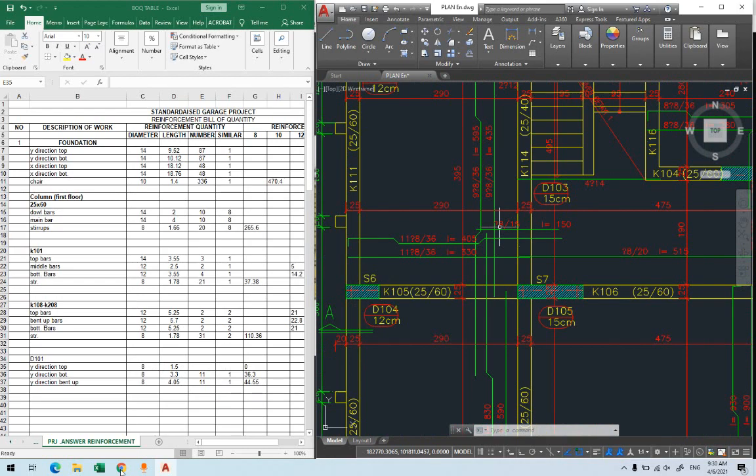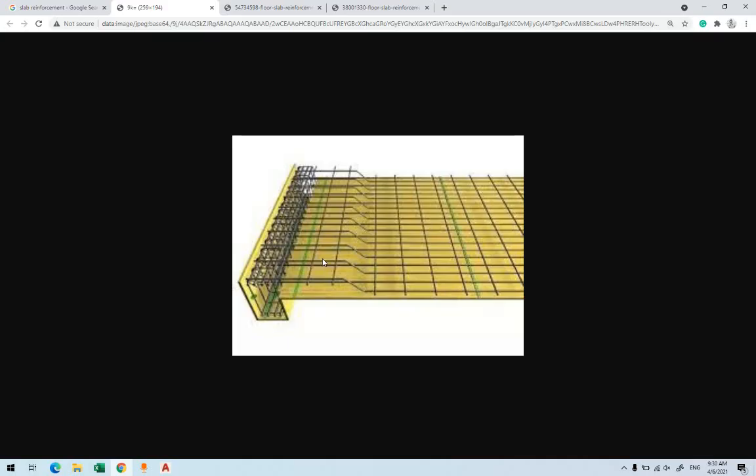I need you first to understand this one here. Those top bars come from where? They come somewhere in between. This is where we place them, because when the bent bar comes, it already is the top, so you put them between the bent bars. Look, the bent bars are already coming there. So when you do, you put one in between the bent bars. This is the top one we have there.